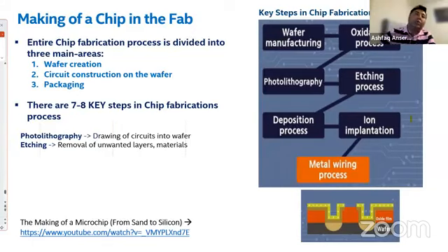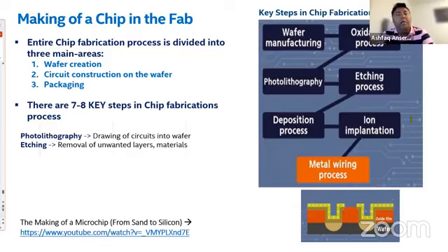So we oxidize the iron so it does not corrode. Similarly, for the semiconductor wafer, we produce the silicon dioxide so it prevents corrosion. At the same time, it produces an insulating layer on the wafer so that there is very, very small leakage of current.